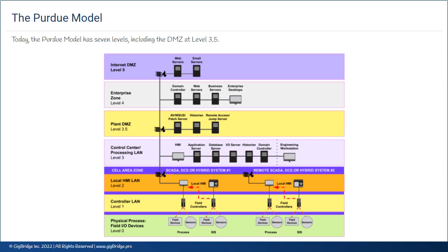As such, level 0 and level 1 are where devices like sensors, actuators, drives, DCSs, and PLCs reside. As you move further from level 0 and level 1, more standardized, traditional IT systems, like engineering workstations, human-machine interfaces, HMIs, SCADA, and data historians, will be found. All of these are working on common operating systems, like Linux as well as Microsoft Windows.